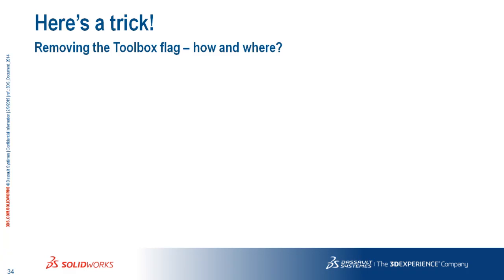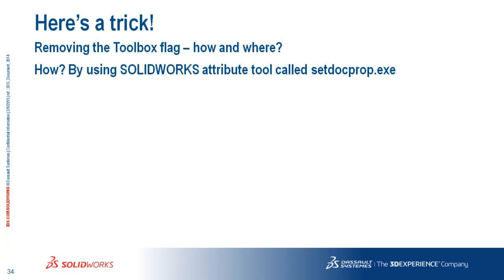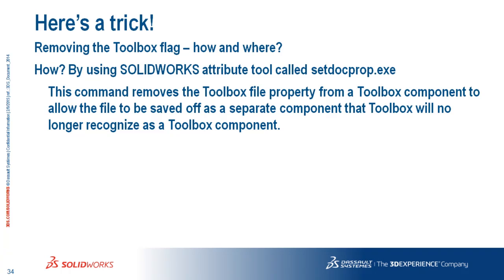Here's a trick. Removing the toolbox flag. How and where? How? By using the SOLIDWORKS attribute tool called set.prop.exe. Anybody use it yet? Oh, good. So where is this? It is the command that removes your toolbox file property, right?